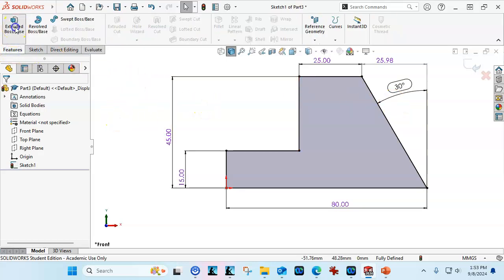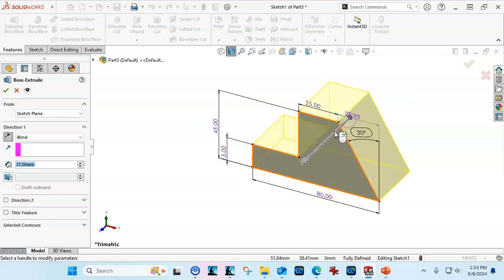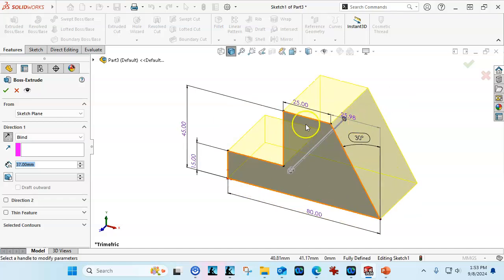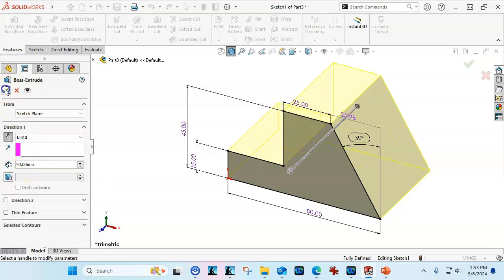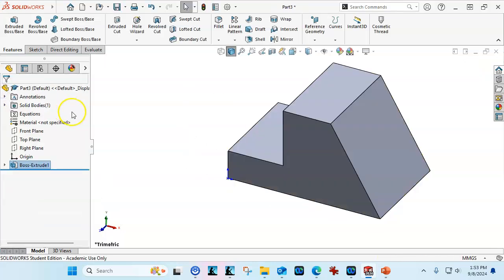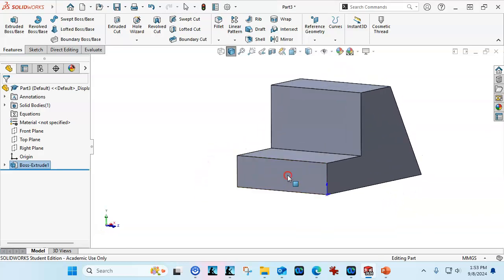All right, so let's go ahead and extrude this out. I'm going to go that way since that's the way I'm thinking about it, and it has a depth of 50. The box is highlighted in blue, ready to receive the dimension. We type in the 50, hit OK, and we have our geometry. All right, so on the bottom side, let's break this up into two segments.